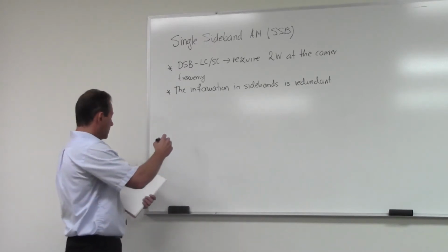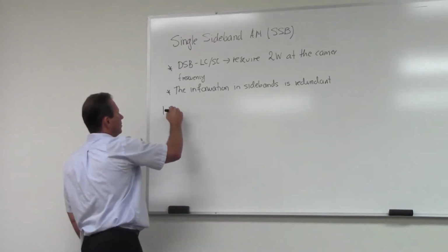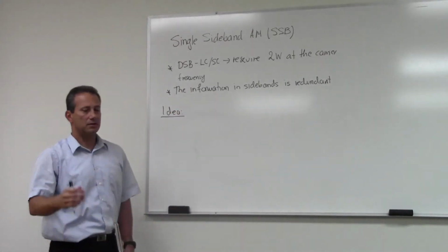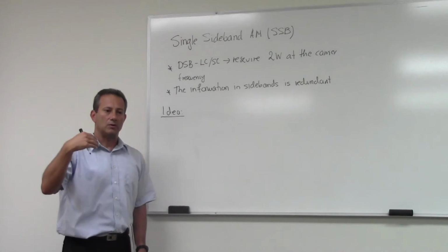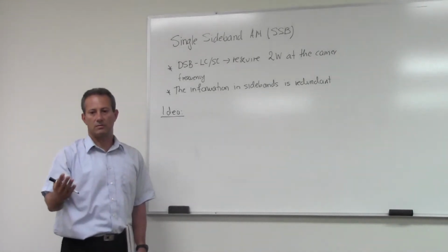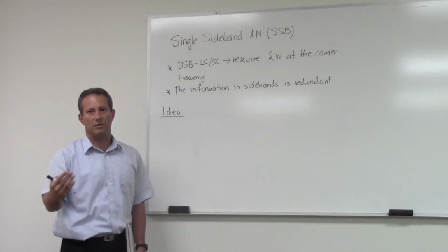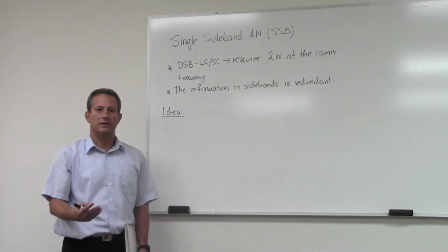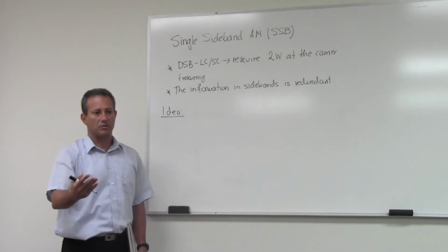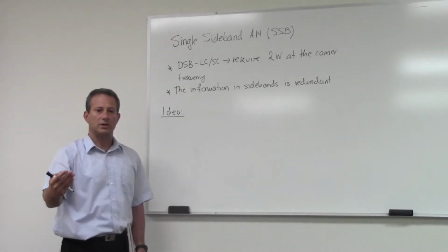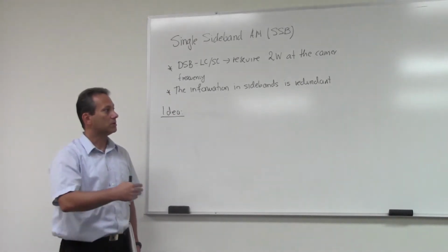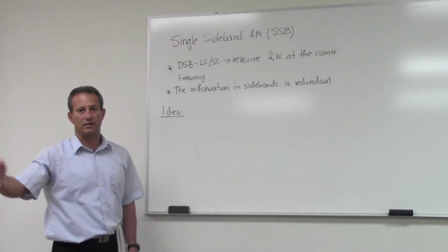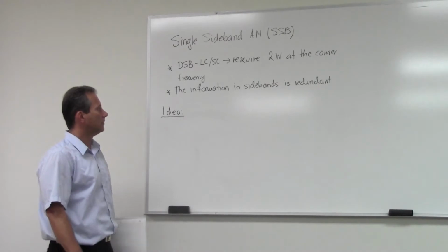So how does the single sideband work? Well, let's take a look at just the basic idea. This is just saying, okay, if I were to do it, what math would need to happen? You will see right away that this initial idea is not very practical, but fortunately we'll be able to go through the math and demonstrate that you can accomplish the same result by processing the signal at the baseband and then translating the resulting signal to the RF frequencies.